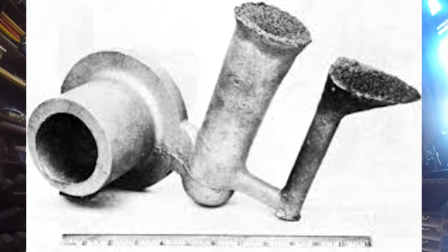You'll either have a wedge riser or you can have a riser put on the side. A wedge riser is a little bit harder to work with because you would have to saw off as much as you can with either a hacksaw or a cut-off saw. And then you'd have to put that casting inside a lathe and form that lip by machining it.